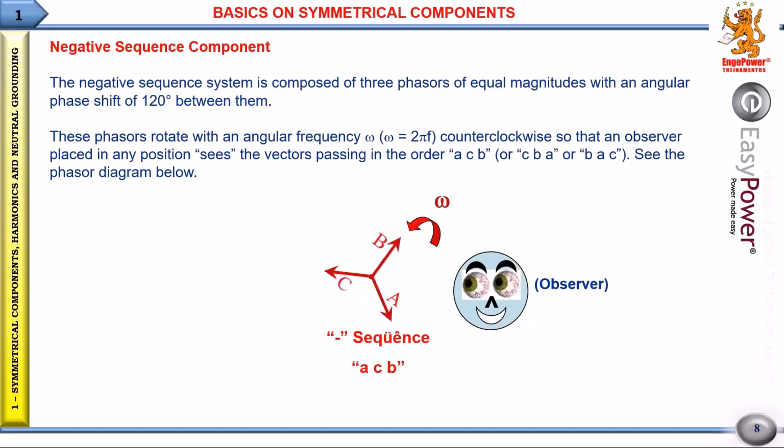Thus, the negative sequence function protection is, in the first instance, thermal protection for stator windings of rotating machines. Negative sequence protection can also be applied for other purposes.